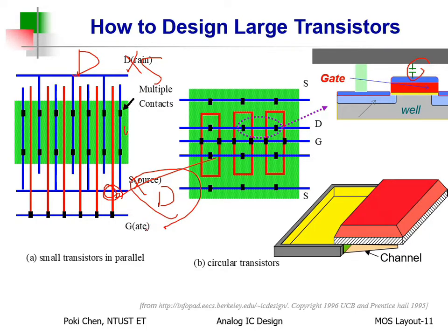So in any case, we can swap it. Okay. It depends on which is the output node, drain or source? Okay, can you use the gate as the output node? No, because the gate does not have any kind of driving capability. It is isolated from all the others. Okay, so the gate definitely can only be input or reference. It can never be output. The output for the transistor needs to be drain or source.